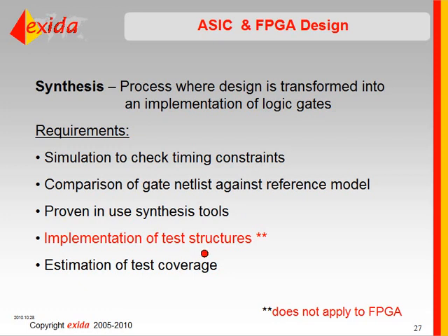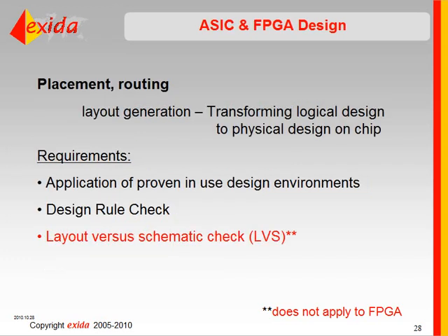Implementation of test structures. In order to achieve that high test coverage in the final product, you essentially need to build some logic into the device that allows you to run tests on the final device, and so those are called test structures. And then you need to estimate the test coverage at this phase to make sure that you're on track for the test coverage you need to meet.